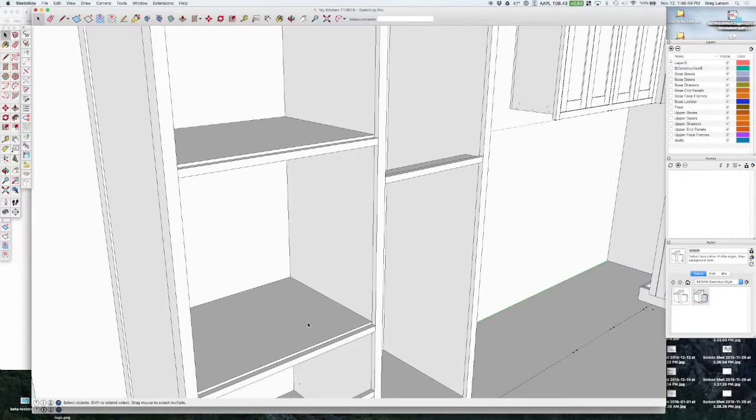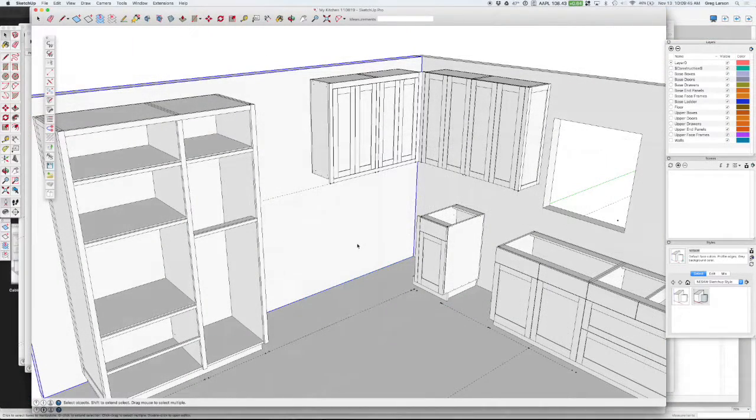And in the case of an open shelf, I just like having that little lip sticking up. I put a little hardwood edge on there and maybe put a bevel, and I don't have to worry about lining the rail up with the shelf perfectly. There's some other interesting things we can do with the divided base tool.